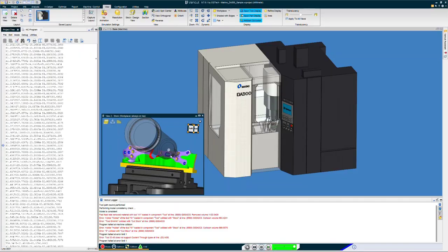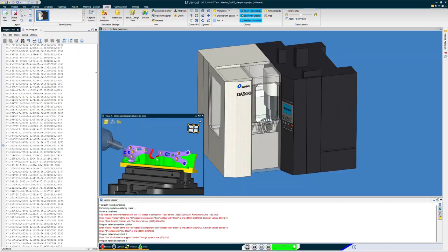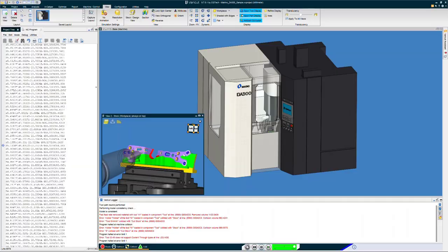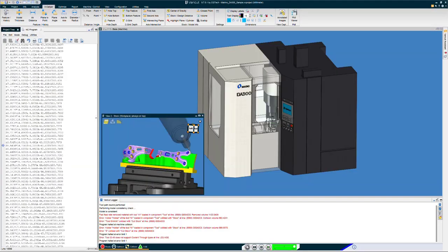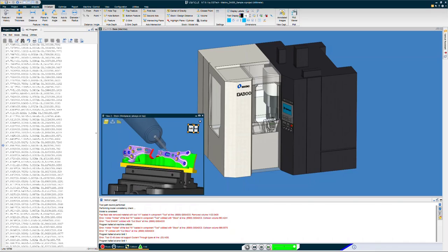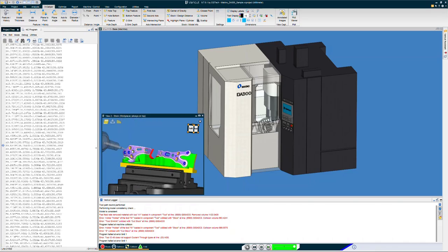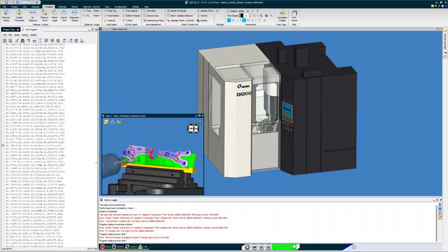As Vericut runs, the digital material removal leaves a cut stock that you can investigate using the X caliper function. You can measure dimensions, circumferences, diameters, wall thicknesses, all using the X caliper function.